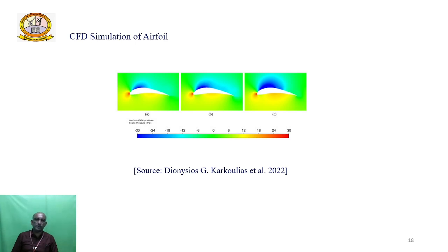This is one example for the aerofoil section flow analysis. Here the velocity contour and the static pressure contour are shown. Positive maximum pressure occurred in the nose portion, the lowest pressure occurs on the upper side of the wing, and another yellow region occurs on the downward or front side. So from that figure we can predict whether the aerofoil will travel in the air.